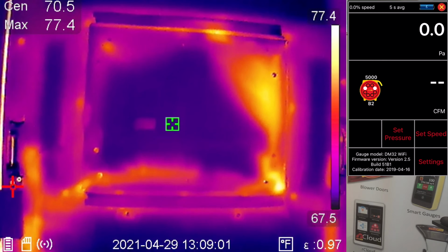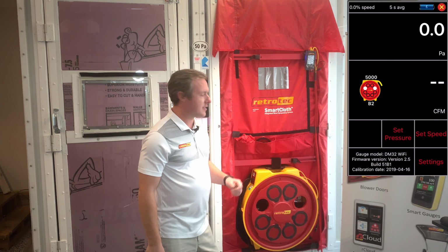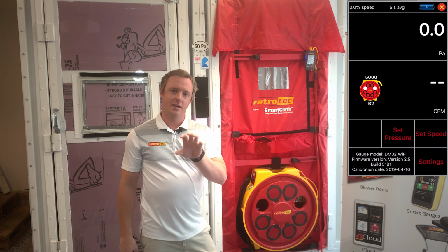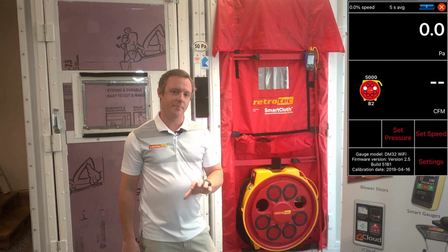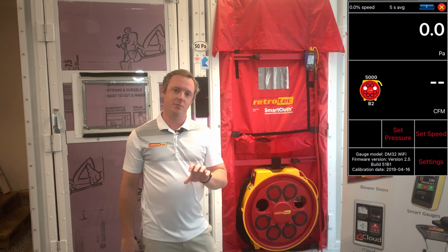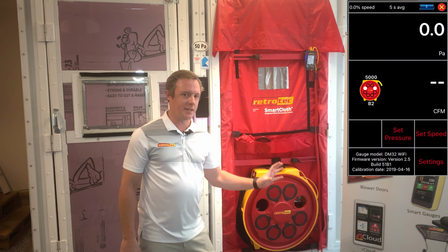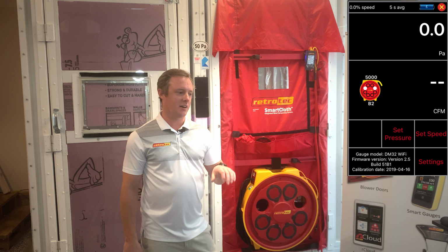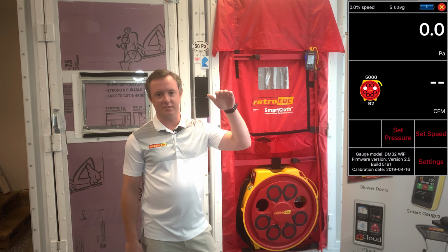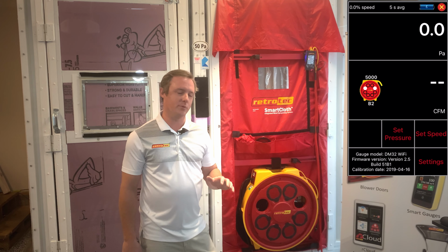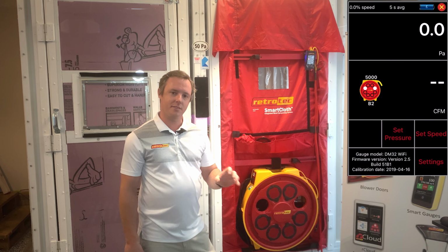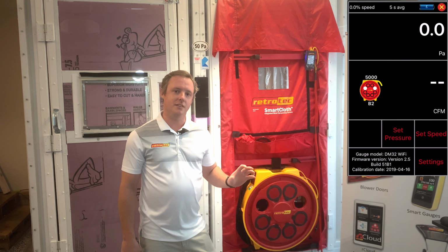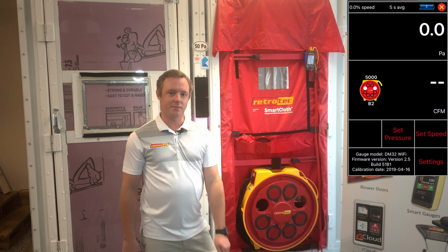And it's for this reason why we don't want to run our blower door test at 50 pascals first and then do thermal. Because then we can't see the leaks build as we increase pressure slowly over time. We're not able to see the severity of some leaks compared to others because everything has already been lit up with that high pressure, and those surface temperatures we're looking at are kind of stuck there for a while. We'll have to wait for the house to cool back down to its natural state before we can do this again. So to work through this faster, it's better to do your thermal imaging first and collect all that data that you want, then run your test at 50 pascals.